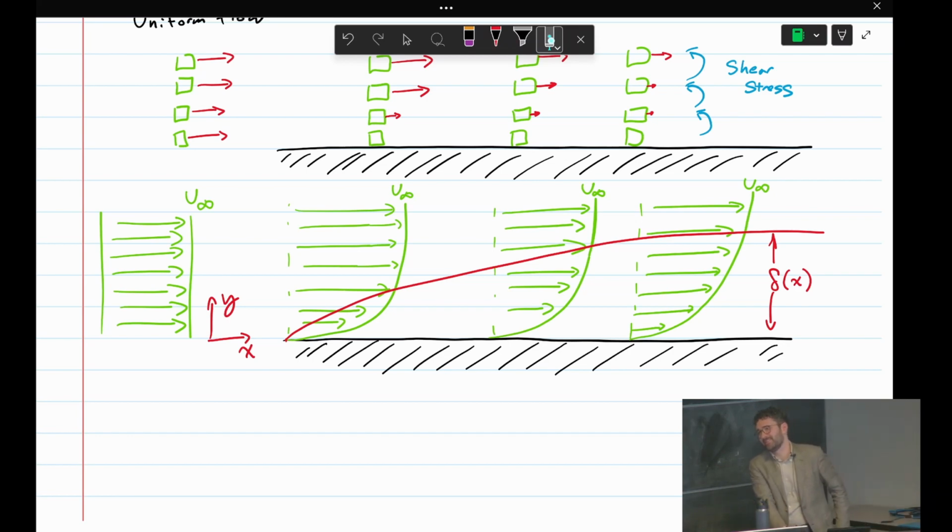Yes, please. You can check the velocity and say this is 99%. Very specific answer. We could check the velocity at a given point in the profile. We say, well, the velocity there is going to be some fraction of u infinity, because we know we go from 0 at the wall up to u infinity. So if we say the boundary layer is always at some fraction of u infinity, then we could define the boundary layer thickness like that.